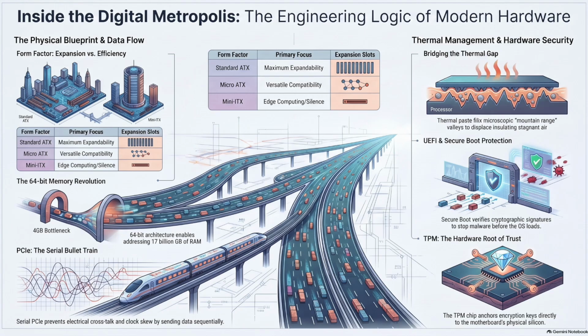But if you drop one of those high-end GPUs into a PCIe x16 slot, the motherboard literally cannot route enough electricity through its own traces to power it. Right. You have to bypass the motherboard entirely and run thick, dedicated power cables directly from the power supply to the graphics card. Usually specialized 6-pin connectors delivering 75 watts or 8-pin connectors delivering 150 watts of 12-volt DC power.